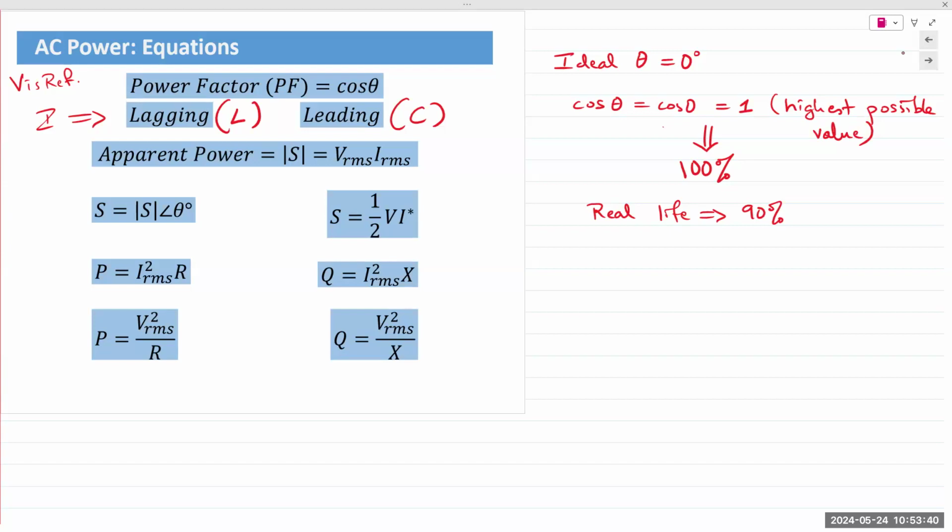Consumer receives 10 units, 3 units go into the resistive portion, 7 goes to the inductive portion. After that, the local power capacitor sends the 7 units to that first machine. So from that point on, the machine only requires 3 units of energy. You guys with me so far?